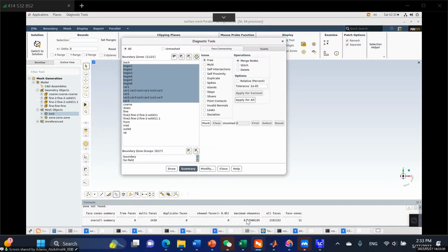And this high value may be due to the geometry. If your geometry has a lot of problems, the connections and edges have problems, the number is going to be very, very high here. So when doing this mesh, we should try to make sure that our model, the train model, is very good. The connectivity is good, the edges are very tight, and so on and so forth.